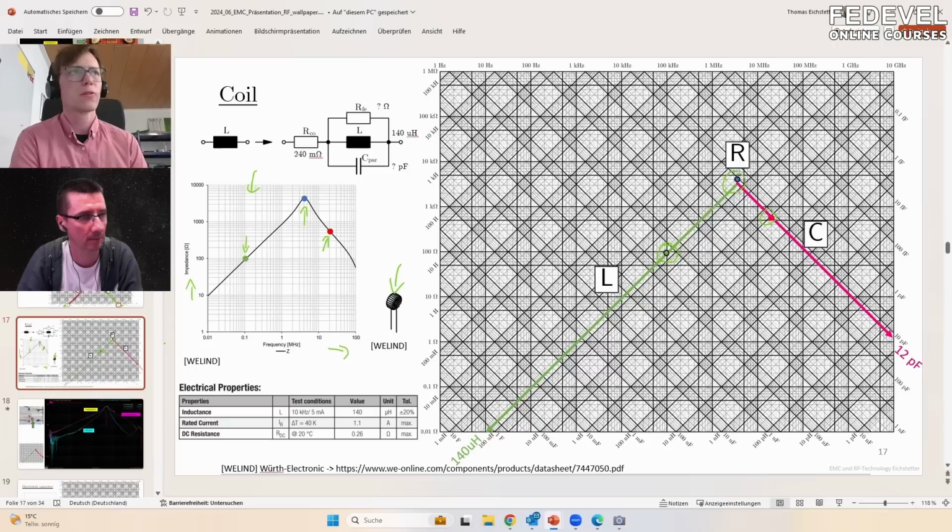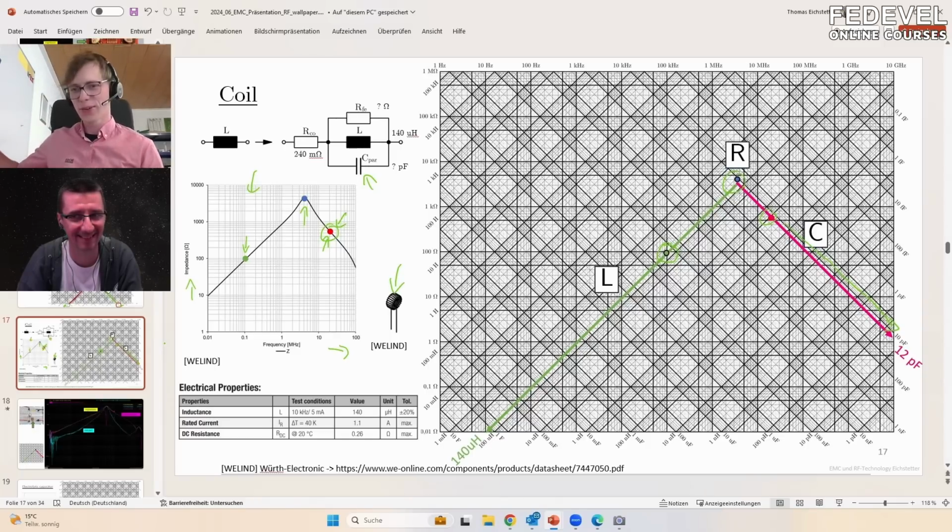And now you can have, with one look, all the parasitics. So you can see what is the capacity, because here on the data sheet, actually no one tells you what is the stray capacity. And with this one here, when you have this point, you go down. So it's the other way around of reading. And you see it's about 12 picofarad. This is actually very interesting. I had no idea something like this exists. It's also possible that you use the calculator here, but as said, I'm lazy. I have it on the side, I use my finger, and in 2 seconds I have the result.